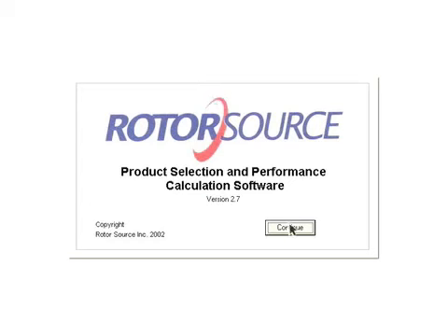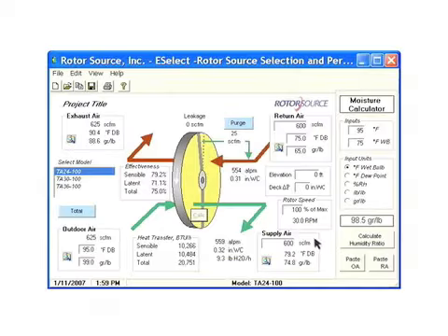Select Continue. The Energy Recovery program features a rough schematic of the wheel and works using parameters for outdoor air, the air which will be supplied to the space, the air which is returned from the space, and the air which will be exhausted as spent exhaust. The program also includes a model selection, which is considered against our drawings, price, schedule, and other aspects.